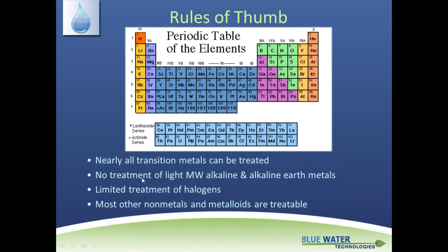There are a couple of things to stay away from. There's no treatment of light molecular weight alkaline and alkaline earth metals. So sodium, lithium, magnesium, not going to be a great application for the Blue Pro adsorptive system. You might be able to get some of that out with precipitation stages up front, but again, it's not going to lend to treatment efficiency within the Blue Pro system.